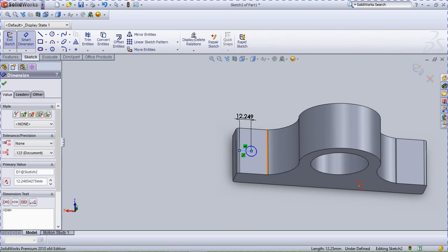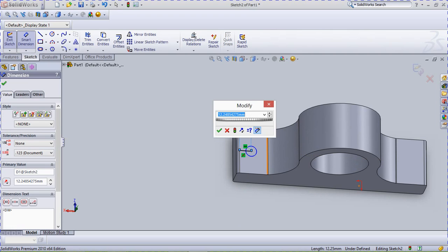Normally I am going to fix a 10 mm bolt here. So a 10 mm bolt means there should be an 11 mm hole to tighten into the flange, which means the base plate will have the tapped hole there. A 10 mm metric thread tapped hole is there. So 11 should be the diameter, and for the bolt head of a 10 mm bolt there should be an 18 mm hole.